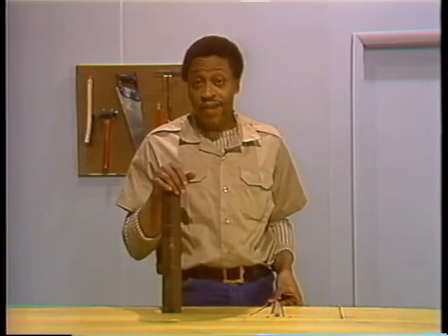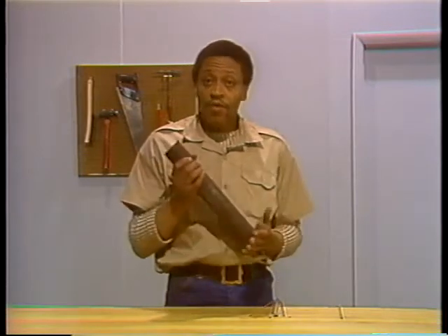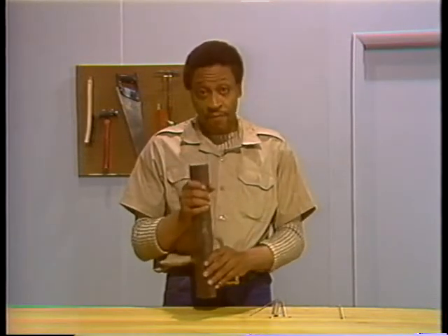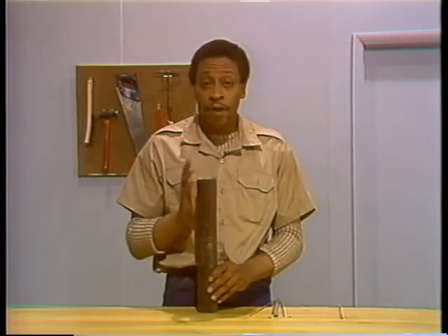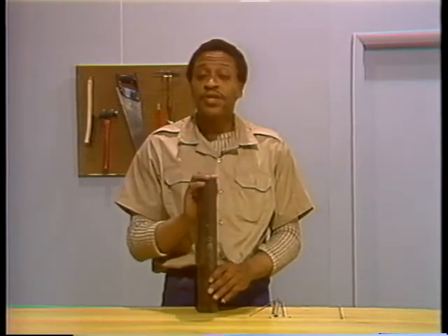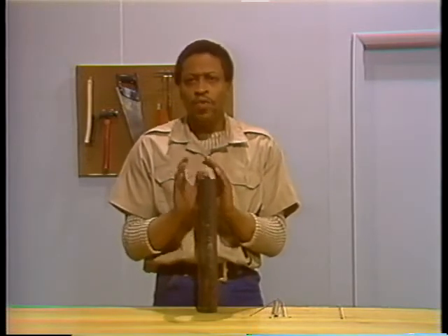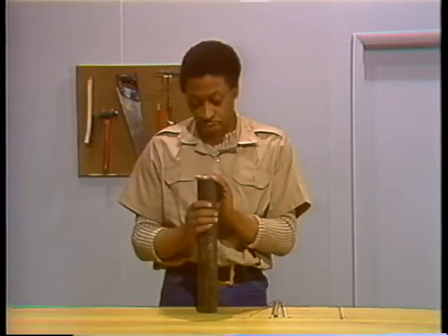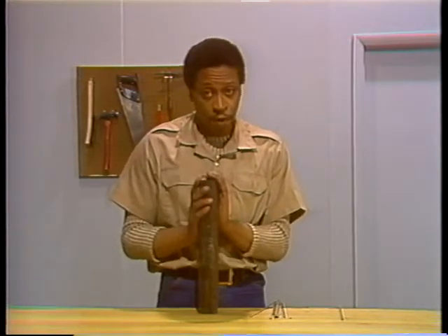In addition to the welding rod, you'll need a replacement tube. The new tube must be the same type of tube as the one that failed. It has to be made of the same type of metal and its dimensions have to be identical. Your manufacturer's manual will tell you what metal the original boiler tubes are made of. Using the right replacement tube is very important.